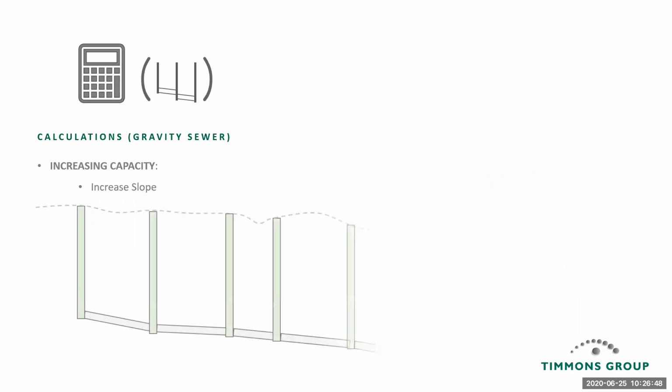It's important to note, when talking about changing pipe slope as a means of correcting capacity deficiencies, that if your engineer comes to you and says, I've used Manning's equation, and based on it we've identified a single run of pipe that needs to be replaced in order to make the system work, your next question should be, have you created a profile?